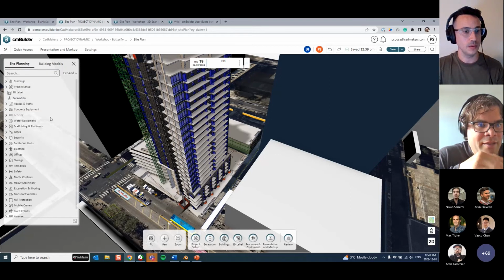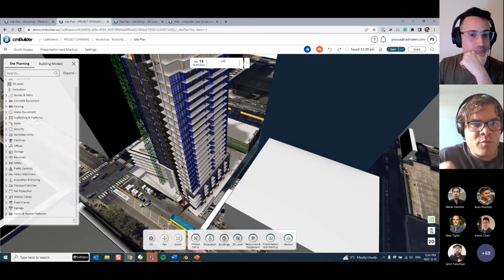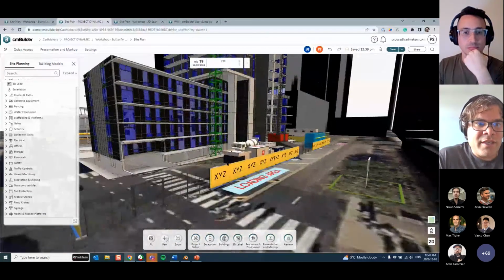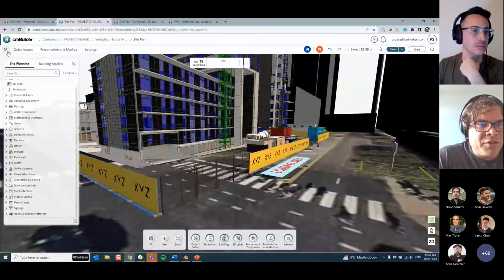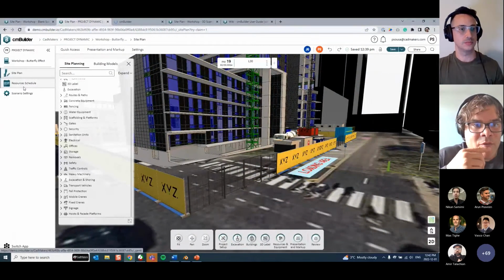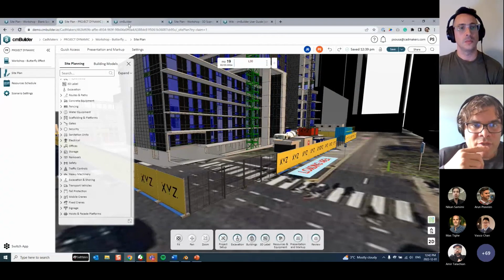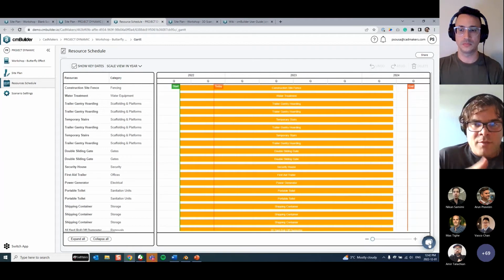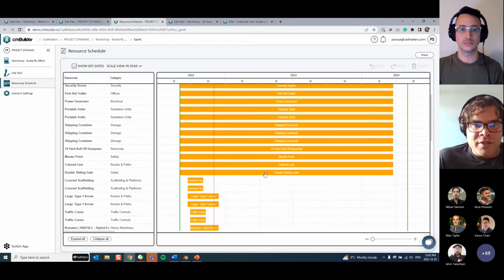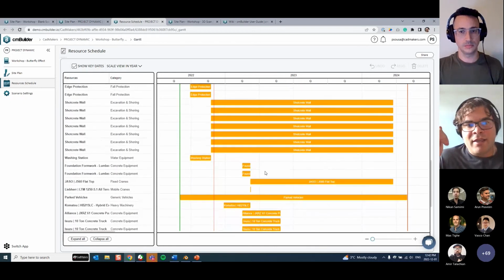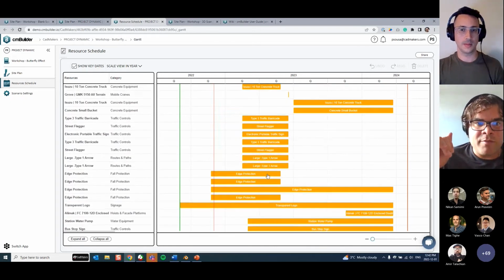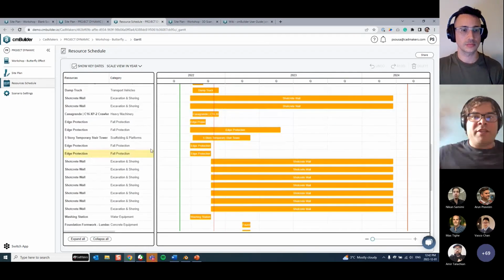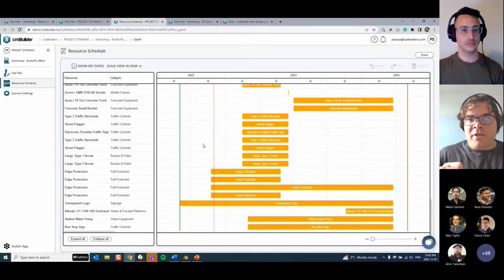You see that you have site planning, and this is where everything that you're adding from the catalog of resources is going. For those who don't know, you can also view this in the resource schedule. We don't need to go too deep into it, but we get this more and more lately. A lot of people don't even realize this is here. So the resource schedule can be pretty useful when you've built out a whole bunch of, like a 100 milestone sequence. It's basically just grabbing every instance of a resource that's been placed on the map and when it showed up and when it left. So if you just want a quick global view of all the temporary resources you're going to use on a job, it's actually being recorded here automatically.